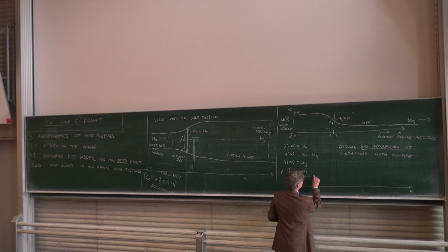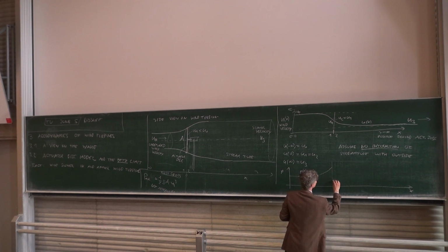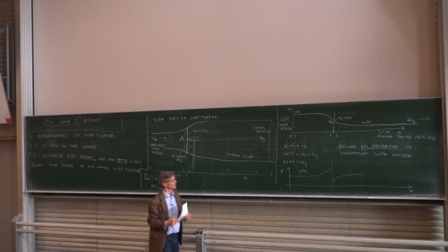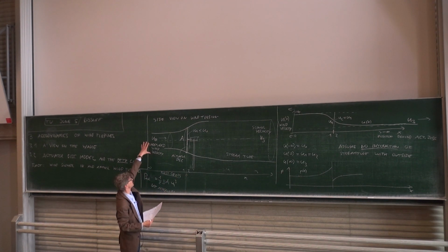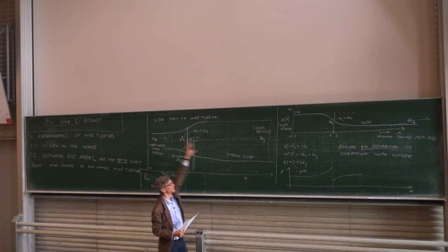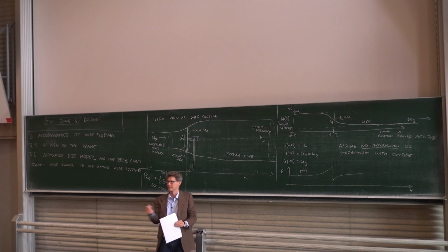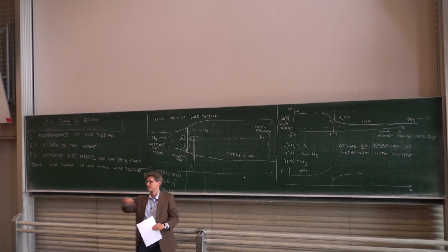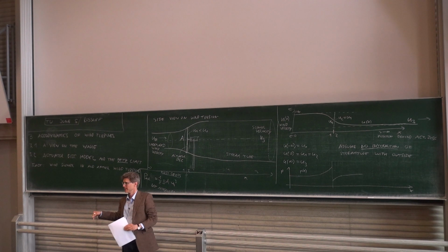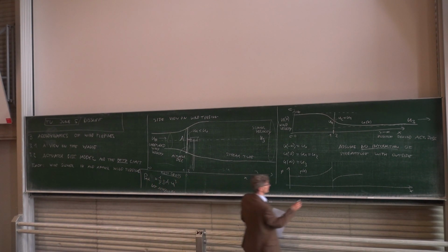Because our turbine gets pushed to the right, there must be a pressure jump at this actuation disk. And interestingly, there is some interaction with the outside: the pressure cannot be different when you are very far away from the outside pressure. When you stand next to a wind turbine, there is no pressure difference. Otherwise, there would be air flowing around the wind turbine all the time, extra wind generated by it. It's not. So what we will have here is